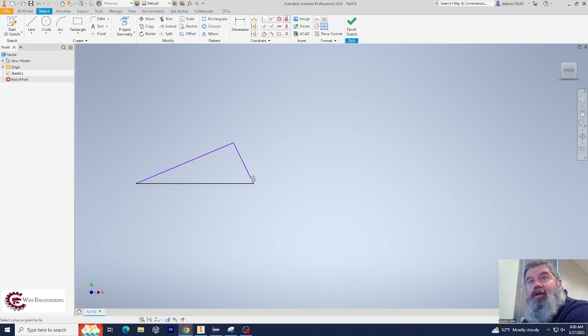They can be used to control lots of different stuff, direction, how the thing looks, all that kind of stuff. Say you want this to go straight up and down. Then you would go to the vertical constraint, choose that line, and now that line is constrained straight up and down. Again, if you want to see what you've done so far, click show all constraints, and now it shows you all the constraints we have set so far. So now our triangle looks like that.